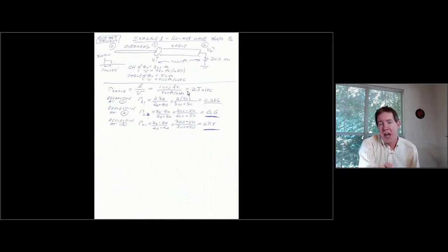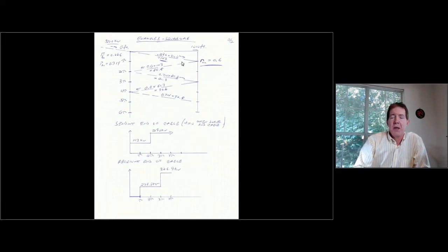So basically what's going to happen is once that overhead waveform hits that cable, it's going to be bouncing back and forth. I'm assuming that the overhead is sufficiently long that I don't need to worry about a reflection from the far end of it. So we're just modeling what happens right after that surge finds its way into the cable section. Now that I've got all the pertinent reflection and refraction coefficients, I would work up my pulse bounce diagram.